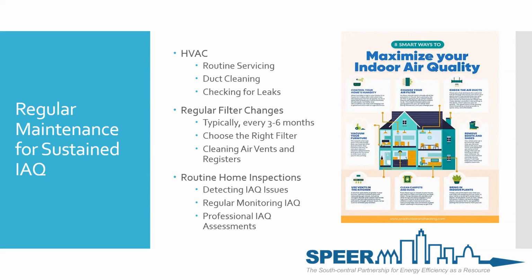Checking for leaks and damages, regular inspections for leaks of ductwork, which can draw contaminants from the attic, the crawl spaces, the basements. And then regular filter changes. We talked about that when we talked about filtration.